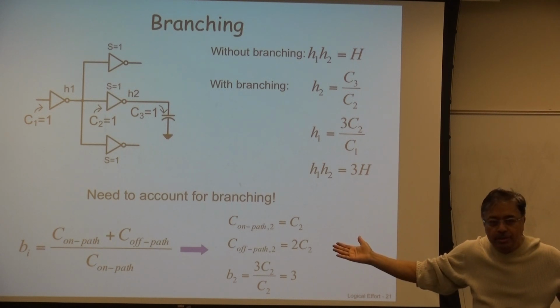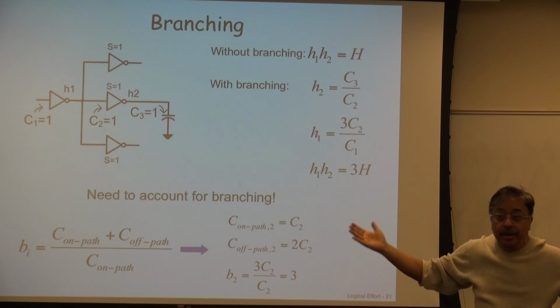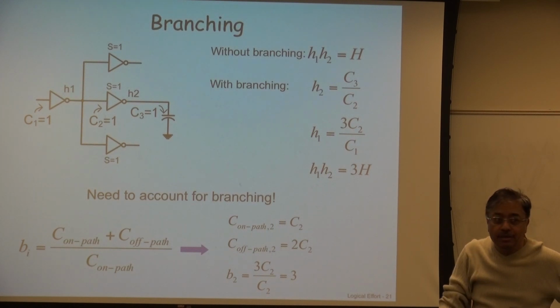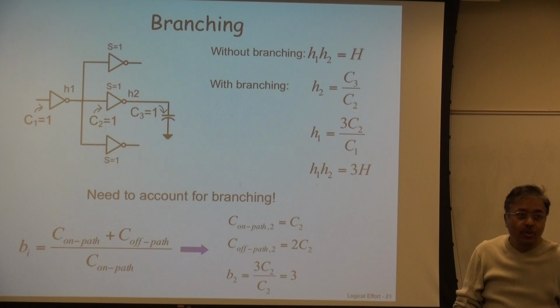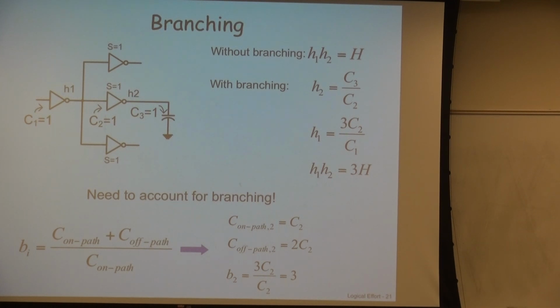Which path do you optimize? Huh? Critical path. What is the critical path? Anybody? What is the critical path? Longest path, right? So, if you have a pipeline arithmetic logic, then you'll have to see between the different registers, the combination of circuits, and which has got the longest delay, right? And that will decide what your clock frequency is.